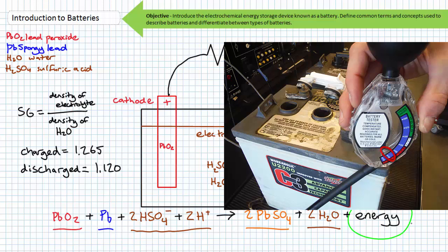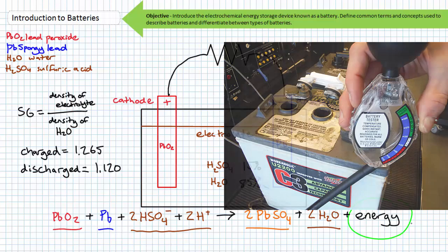The hydrometer is again measuring the concentration of acid internal to the cell, and an individual making use of a hydrometer must take necessary precautions to prevent a spill or splash. Wear the proper PPE and move purposely and cautiously when taking a hydrometer reading. This cell has a low specific gravity reading, meaning the electrolyte is more water and less acid. The other cells show similar readings.